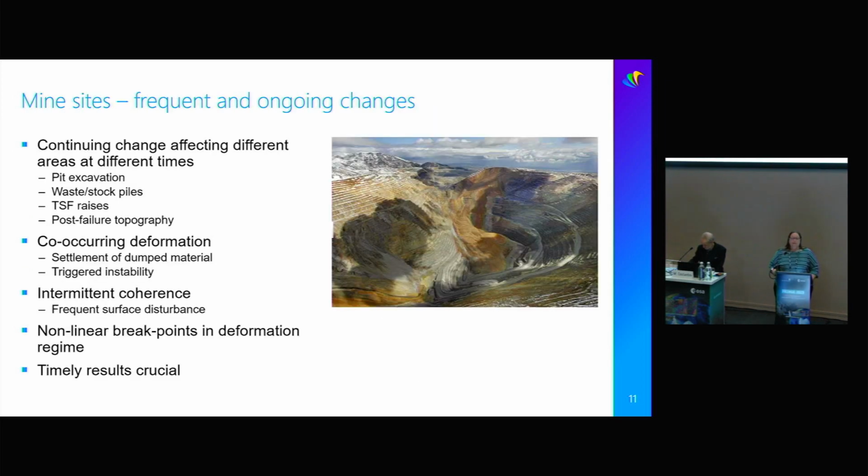Mine sites are particularly tricky for elevation change, partly because the point of having the mine is to try and change the elevation. But there are lots of different processes that go on. They excavate the pits, but they also have waste piles and stockpiles. A TSF is a tailings storage facility, and they are often built sequentially, so every few months to few years, they will raise the level of essentially the dam holding back the mine waste.